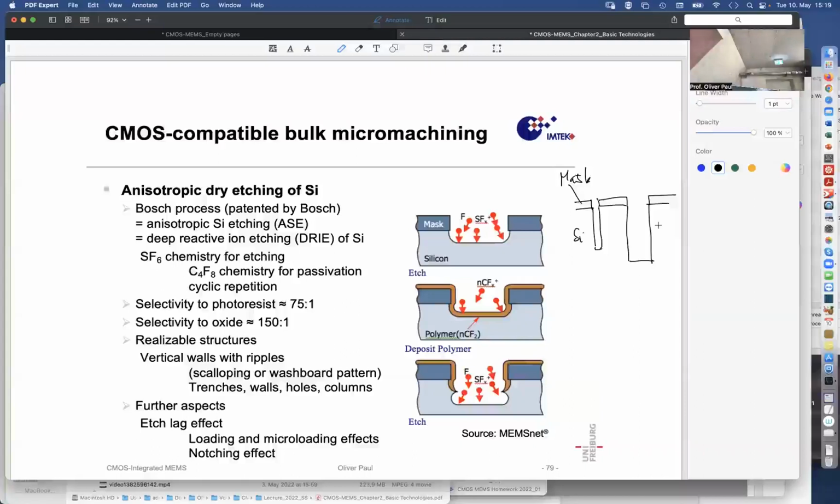So although you would say, oh, there is a little bit of difference depending on the geometry, and the width of the channels or the width of the holes is one aspect. If you're etching not holes but channels, the width of the channel is an aspect, and the difference of these etch depths that you achieve is called the loading effect.